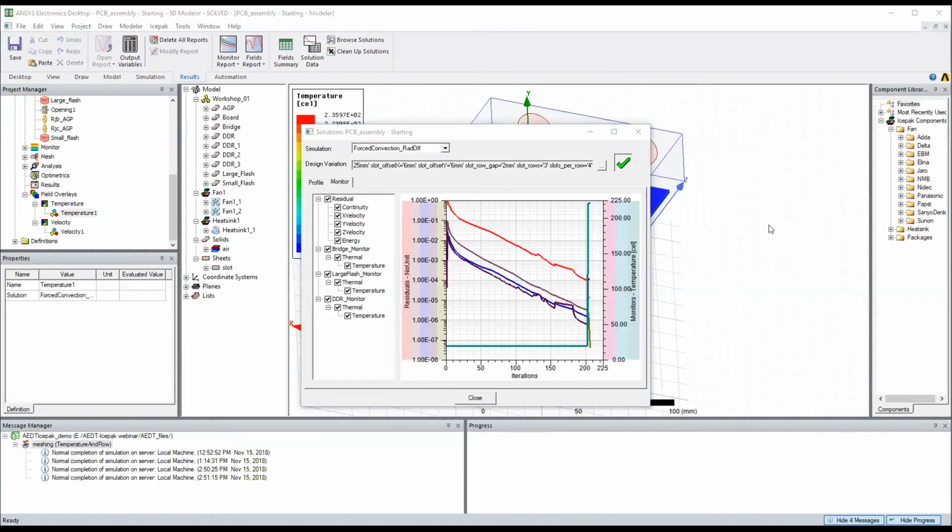I know there's one that asked what HPC is, that you mentioned at the very first. HPC is just high performance computing, and it's where you're taking a model and breaking it up and allowing multiple computers, or it could be one computer with 8 processors, or 8 computers with a single processor. You're breaking the model up and allowing multiple CPUs to solve it. And that's one thing CFD lends itself to, parallel computing, or allowing multiple processors to work on a model. It's very good at that.